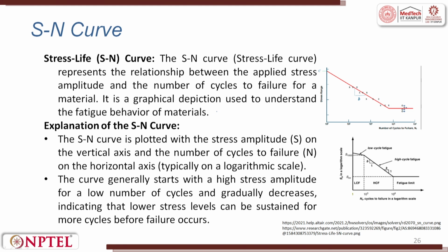The graphical depiction used to understand the fatigue behavior of the material is the SN curve. It is plotted with the stress amplitude on the vertical axis and the number of cycles on the x axis. Many times the horizontal axis is taken in logarithmic scale.